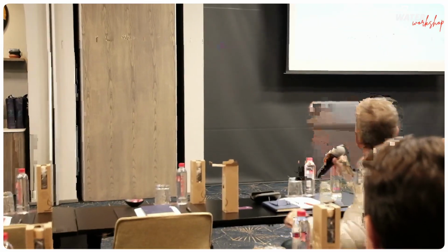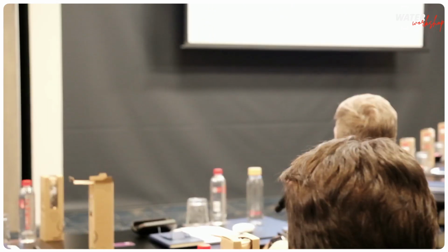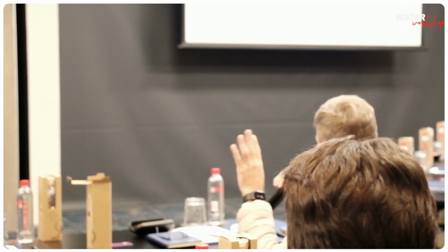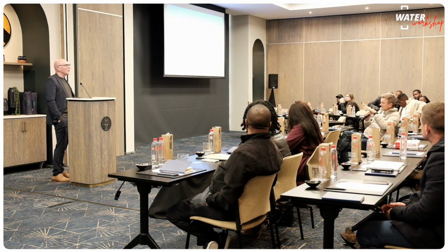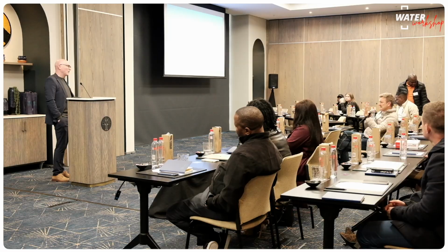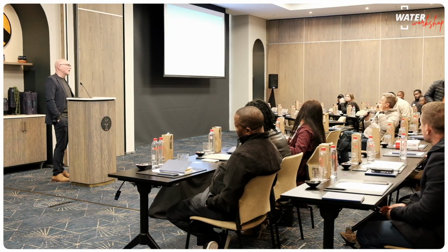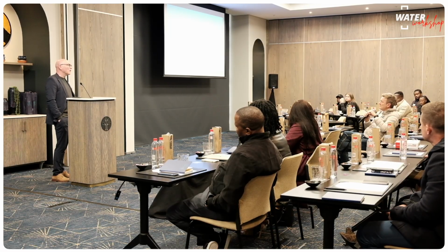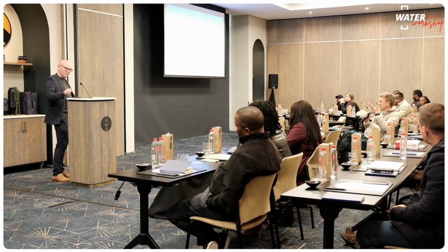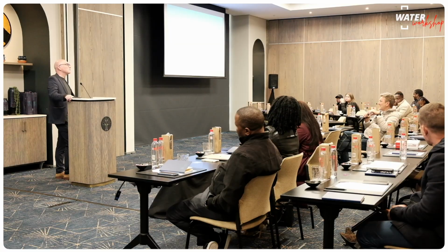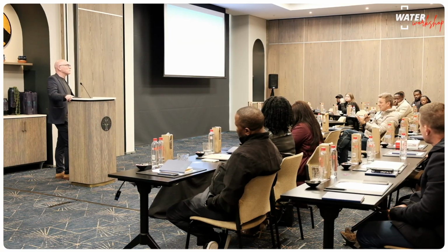Yeah, thank you. That was cool. I've never seen those surface pictures like that with color, really interesting. Just a quick one. You showed that one of the images was gypsum scaling on an RO, a calcium sulfate scale on an RO membrane. Have you also looked at gypsum? It is a big issue in mine water in South Africa in particular, and a lot of the mine water plants are operating at high recovery with anti-scalants, and then trying to precipitate the gypsum out of the brine,